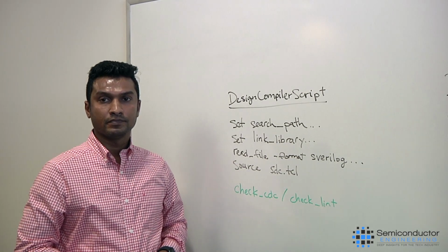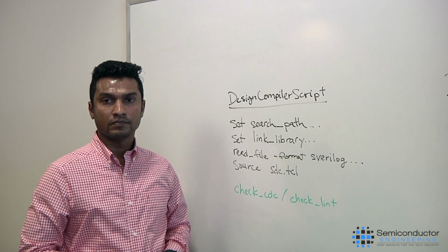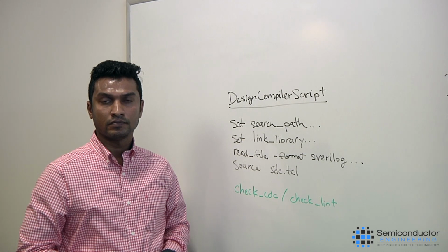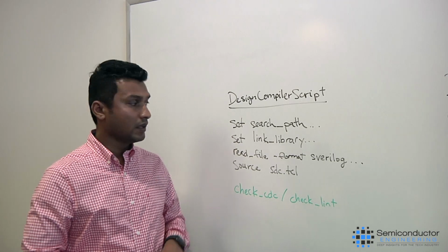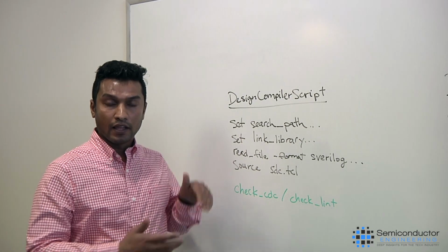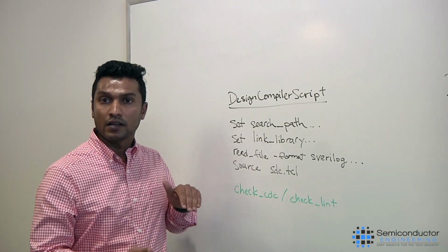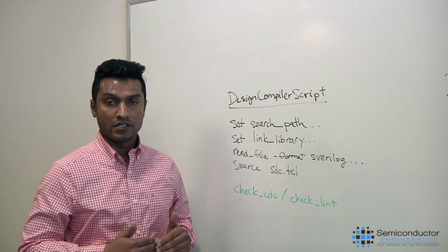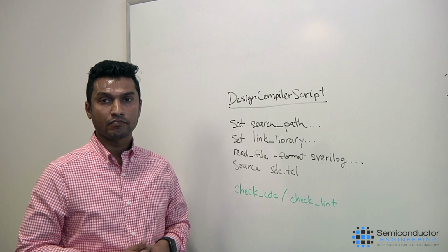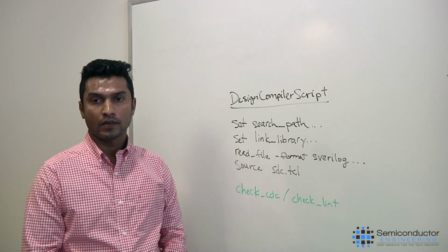Does the team makeup that would be doing these two different functions change at all? Is it still the same? You have design engineers on the front end and then you have verification engineers on the back end, or are you now combining them to the point where somebody can do both? Yeah, so I think even design engineers, if they can add just the check CDC and check lint commands, they can compile the design and run VC SpyGlass for CDC and lint verification. So really what you're doing is you're enabling shift left, right? Yeah, that's exactly correct. Let's drill down into this a little bit more.